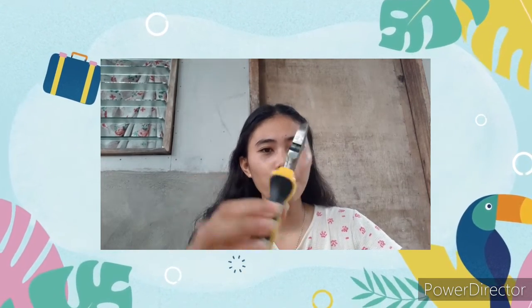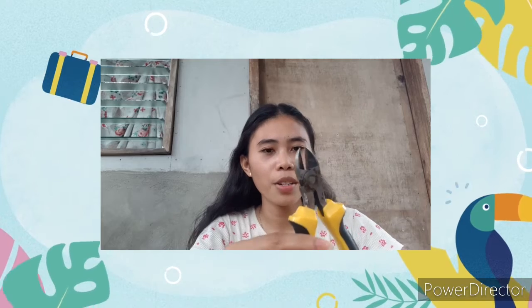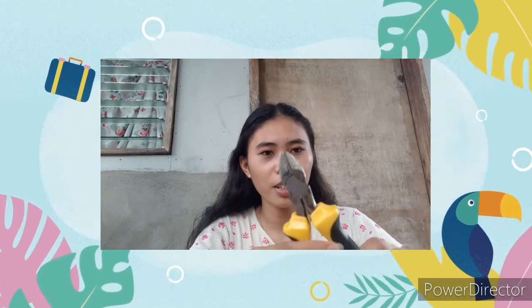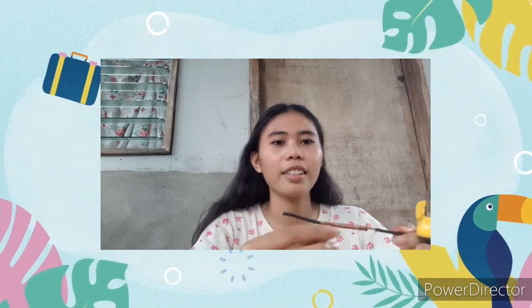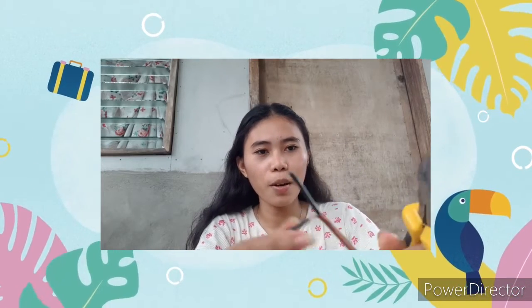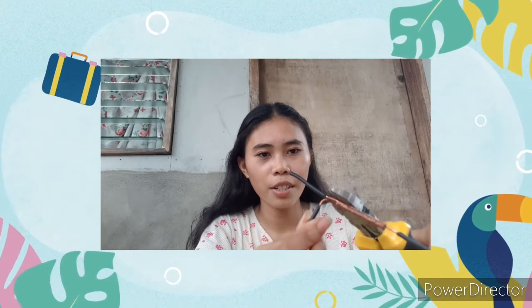For the next tool, I have here diagonal cutting pliers. It is used to cut wires and small pins that cannot be reached by larger cutting tools. For example, I have here this one, the Y splice. I will cut these small pins using the diagonal cutting pliers.